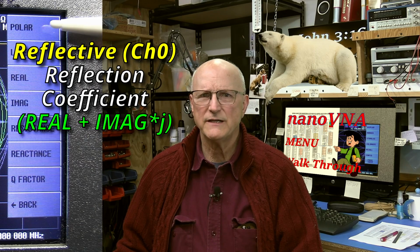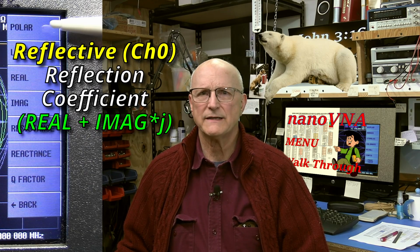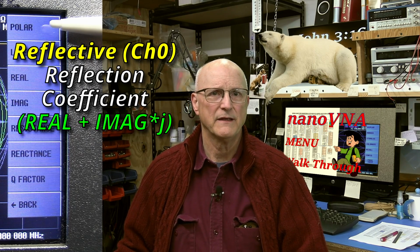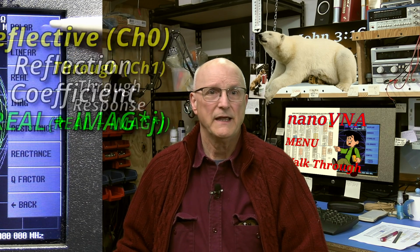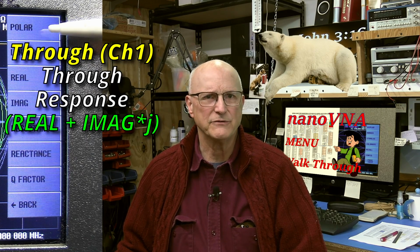These are normalized values. The angle that the resulting vector makes to the positive horizontal axis for any given point is the phase of the reflection coefficient at that frequency. The length of that vector is the magnitude. In through mode, this is showing us the through response in terms of normalized values.